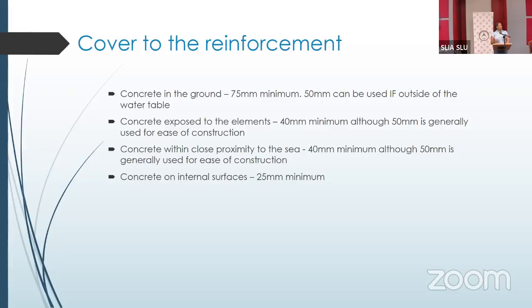If it is concrete on the inside, then we can get away with the 25 millimeters once it's on the inside. Any concrete that is exposed to the elements means that it's not in the ground and it's not inside. So anything that's exposed to the elements, the wind, the rain, the sun,